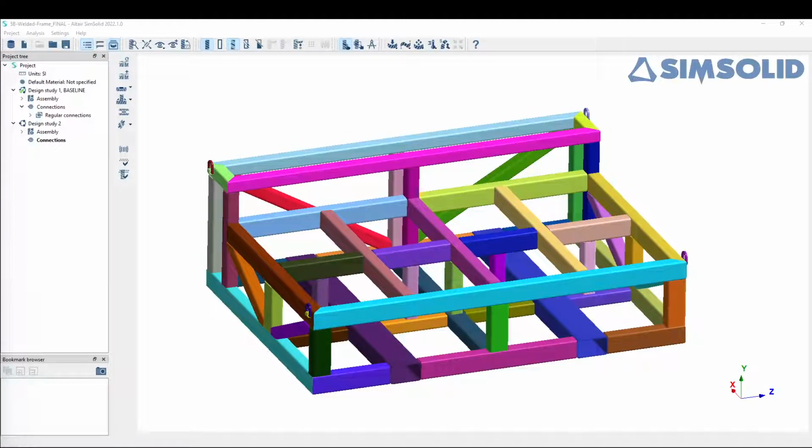Hi, now I'm showing you some tips and tricks for SimSolid contact checking. And why contact checking is important is that you might have had cases where you have used too low contact tolerance value, or there might be parts in your assembly which are not aligned properly, or maybe you have used too low contact resolution in some studies.